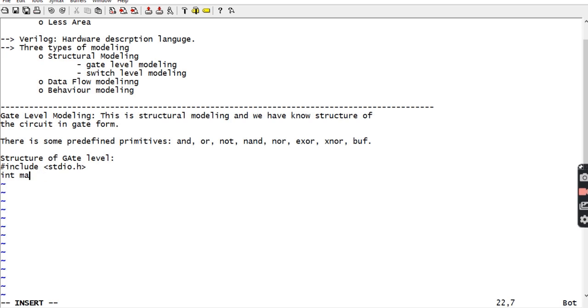So same here, I am taking the example for Verilog. In Verilog also there is some defined structure, in which you have to write module. Here we have to select the module name. And here we have to give the port list. Here a semicolon, and here should be endmodule. So this is the structure, and here you have to define the direction.